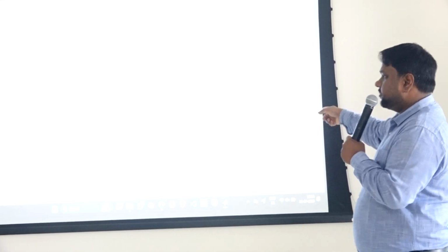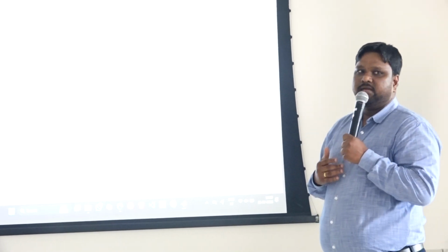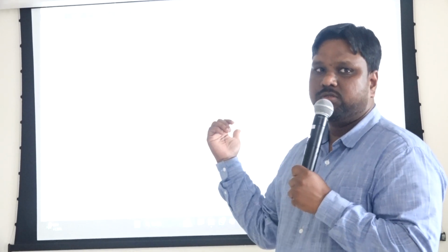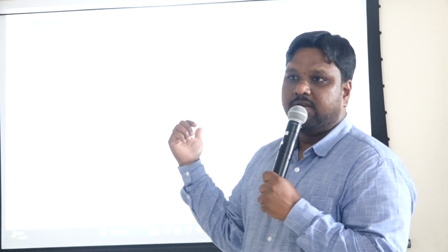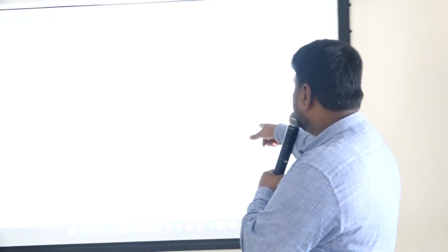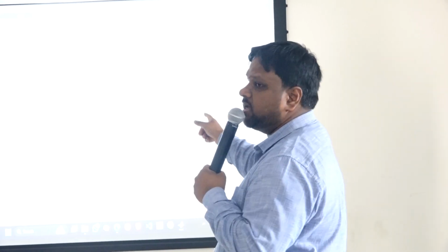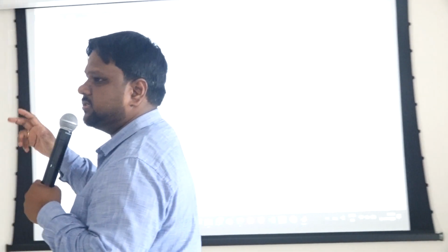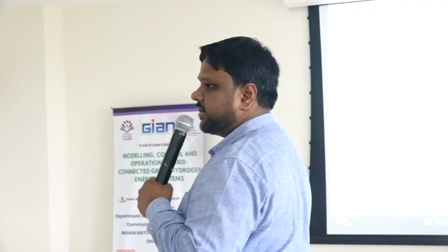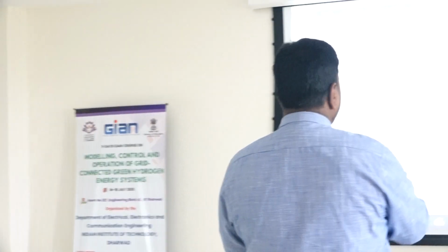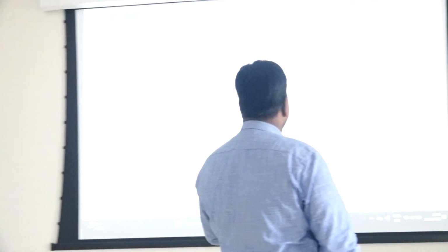Okay. So if I am taking switch 1 as a reference, I will give a phase delay with respect to switch 1 and give that to switch 5. Getting? So that delay we give here, but that delay has to be in terms of second. Generally when I say phase, it is radian or degree, but we have to convert to second. Okay? So first of all, let us understand the mathematics.